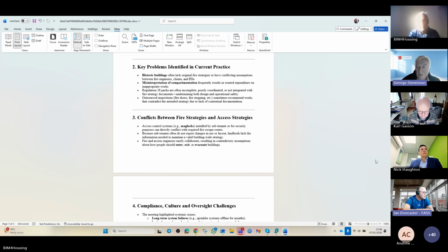A really good example recently: I went to test a basement system, and it had been commissioned, and they put ceilings up that isolated the extract system from the areas it was supposed to work on, and it had all been signed off. It'd been signed off by people that did fans and ducts, and they'd clearly been done when they commissioned it, and they'd signed it off as doing whatever it did, because no one was looking at the whole system. Yeah. So that's new build buildings, whatever sort of buildings.